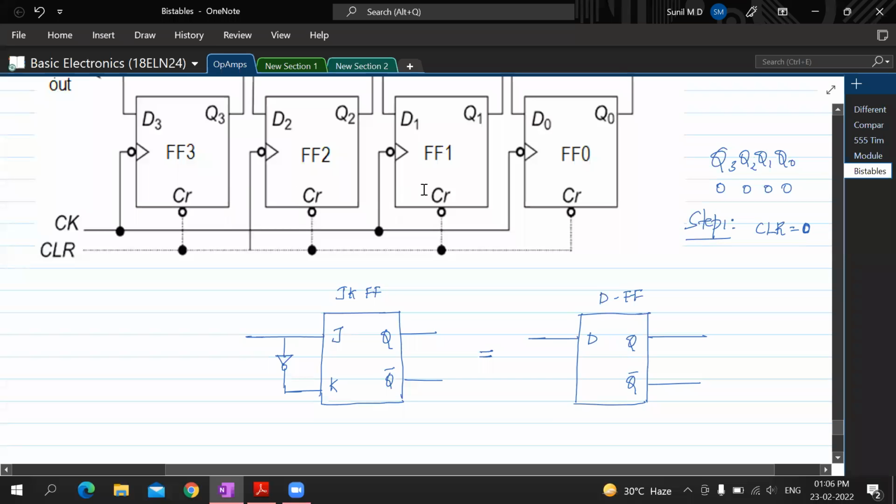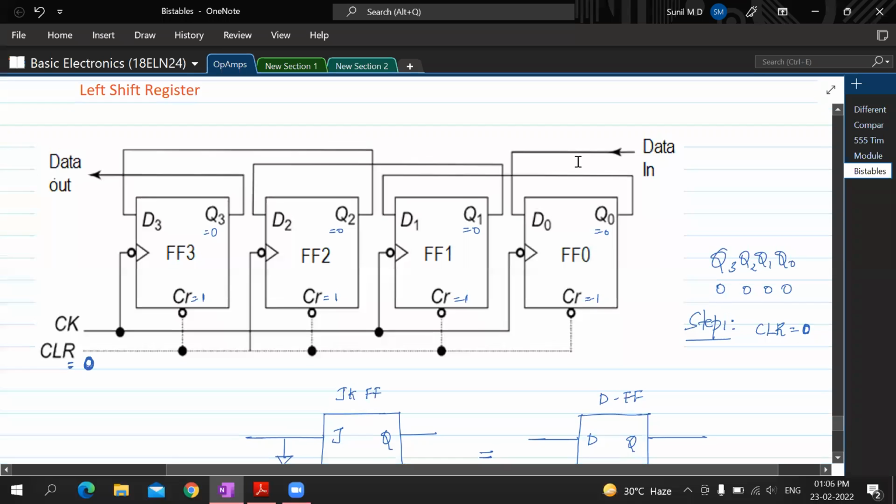After this inverter, if you give 0 here, understand I'm writing that here, if you give 0 to this clear, it would become 1 here. So these are all clears. When they become 1, all the outputs here would become zeros, is what one should understand. Is that okay with you? So this is what is done to begin with.